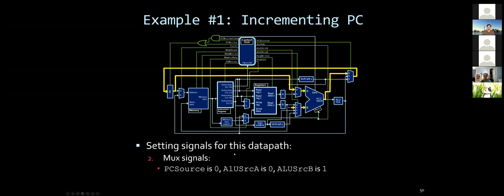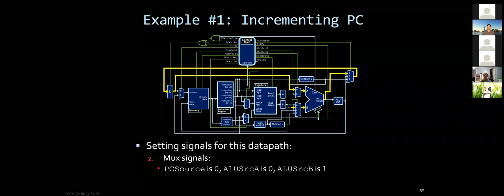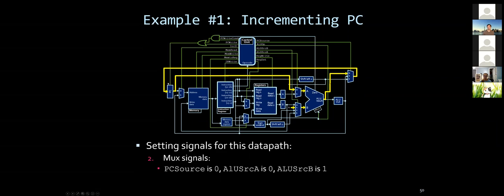And here PC source is 0. So this mux unit, I want to take this value, not any other value, and that value goes into here. So it's really a very tedious process, but there's no black magic here, right? I really need to draw the flow I want, and then I go and write step by step each flag I need to make this happen. Okay, any questions here? We're going to do more complicated examples, but that just shows you what's happening in the processor.